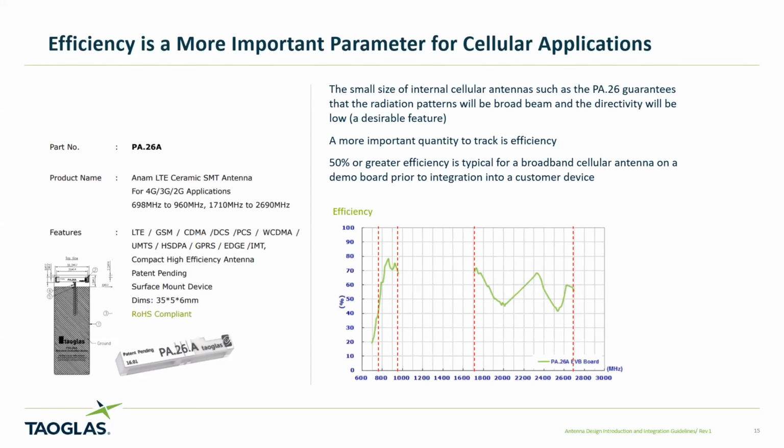The gain would be the directivity minus losses. So if you had a pretty well-designed antenna that had 1.5 dB of loss, you would wind up with an omnidirectional antenna with a gain of minus 1.5 dBi. And then you would use that gain in a link calculation to verify that the cellular system and that client device will make the connection and support the bandwidth you need.